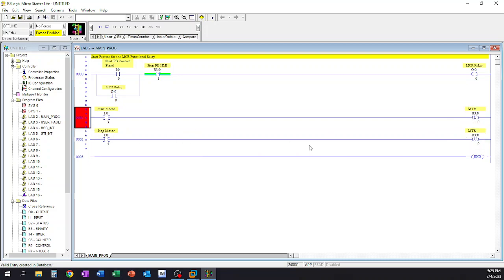With that being said, I often caution a lot of people in putting latches and unlatches in programs. They work great, they look great, they function great. The problem is that sometimes we'll put a latch in one routine or ladder, and the next thing you know, the unlatch is somewhere buried deep in the program, and it makes it very difficult for people to troubleshoot and understand.